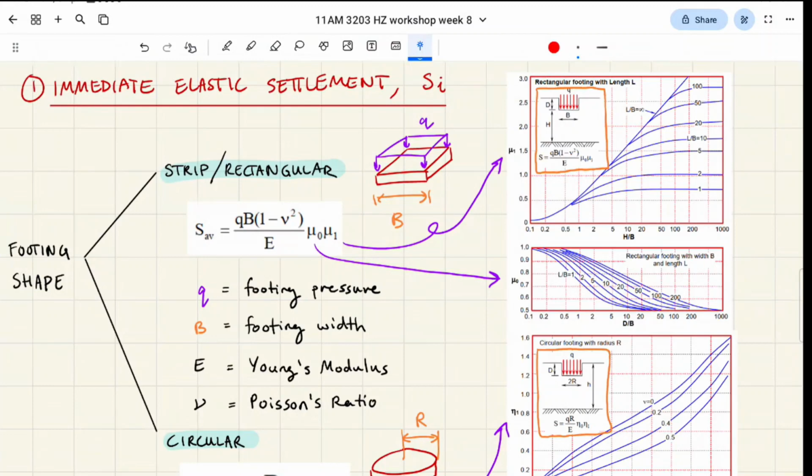So this amount and this amount added up, right, is going to be, for example, 0.3 millimeters, right? So you squash it down 1 millimeter, it fattens out 0.3 millimeters. That means you have a Poisson ratio of 0.3. That's what Poisson ratio is.